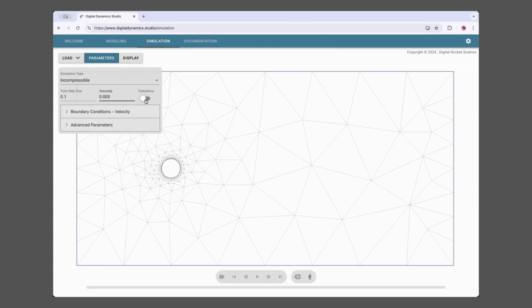We're not going to talk about that or use that in this simulation. The documentation talks about that, but for very high Reynolds number flows, there are going to be lots of very small features in the flow that no mesh, not any mesh, could actually capture. So all you can do is model their effect on the flow. For very high Reynolds number flows, you might want to enable the turbulence model, but we're not going to use that or talk about that here. The documentation covers that for people who are interested in those kinds of options.